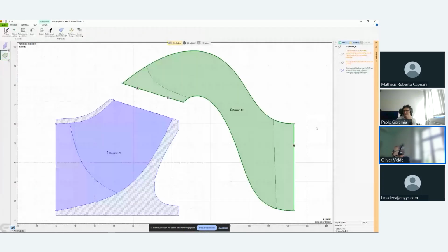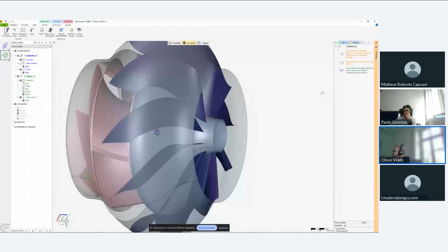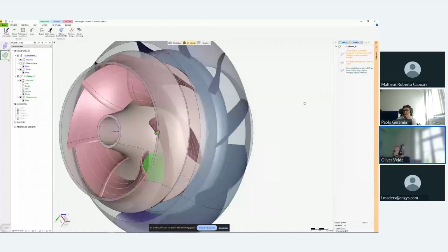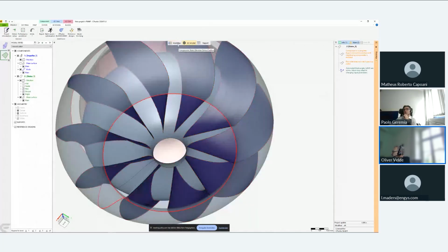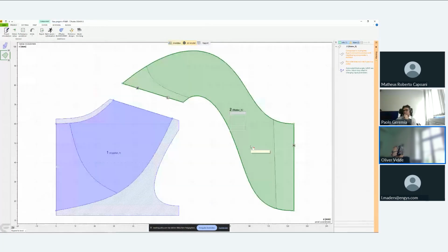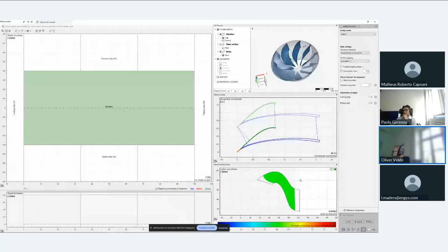In 3D, I see the same situation I had before for the impeller, but this time for the vane diffuser with 0 thickness. And in order to save a bit of time, I just go quickly through the last 2 design steps, blade profile and edge design, by just using that last soft button, which allows to finish the design based on all default settings.